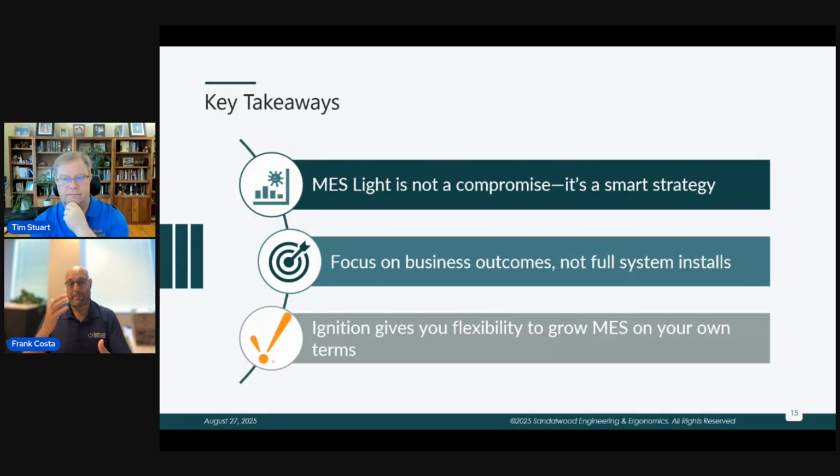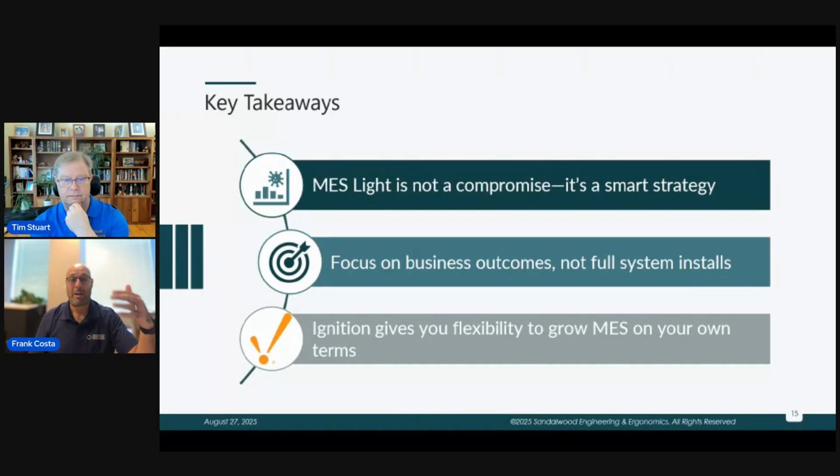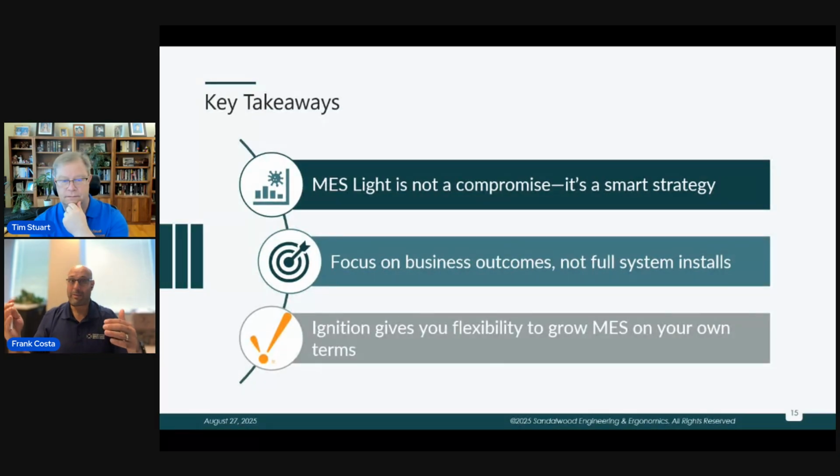And when you go through, I'm going to focus on a SCADA implementation. If you set up a UNS correctly, it doesn't matter how many machines, because I know where all the information is landing. I don't want to get too far into a UNS conversation. You think of it as a hierarchy, a folder structure. I know my sensors go here. Any inputs from my sensors, my parameters go here. My build data goes here. You set that up, and then you can grow your modules to say, all right, my SCADA is only looking at machine metrics. And then when I look at quality, I'm looking at this directory.